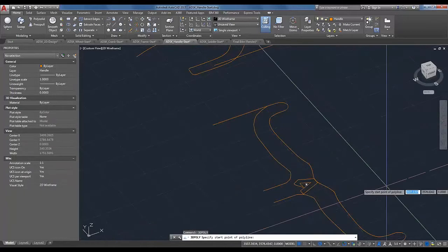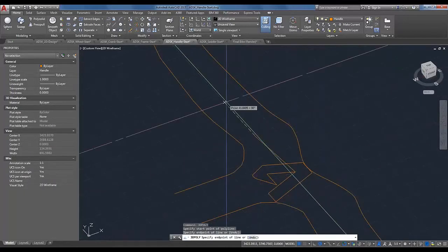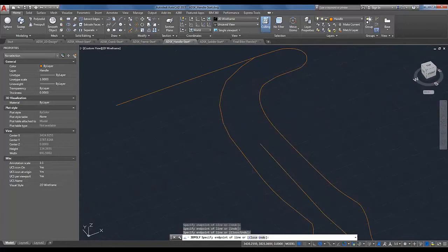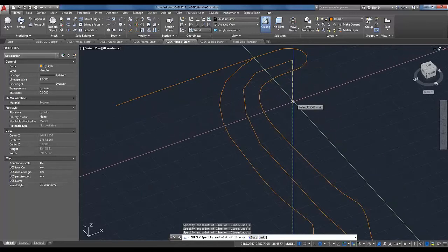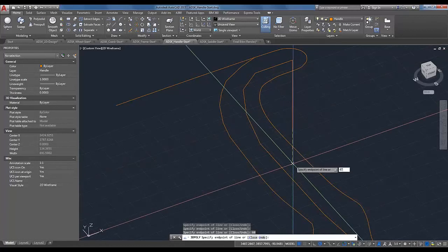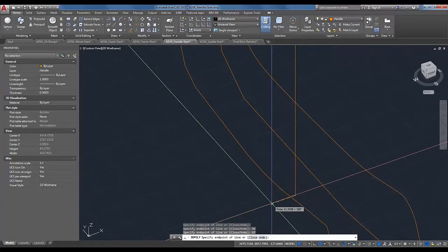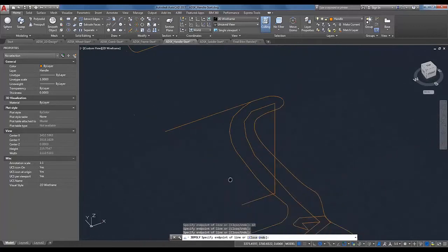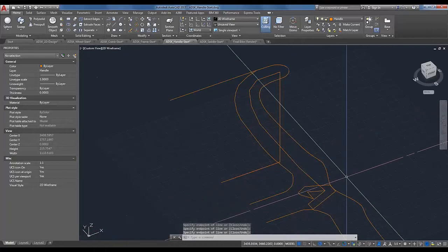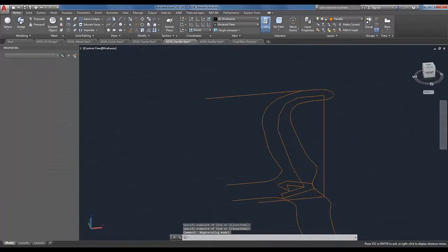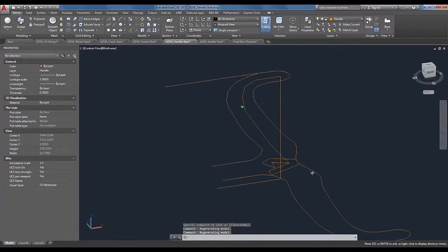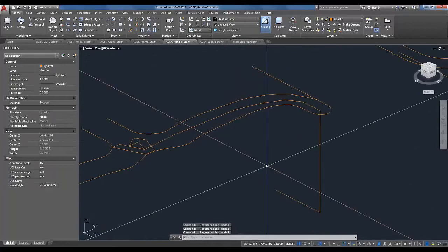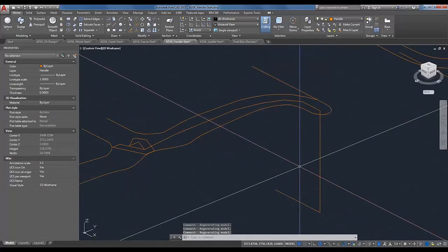3D poly. Going to create kind of a center line. I'm going to go down Z. Let's do 60 first and then 67. And then I'm going to go back, just creating some nodes along the way. Enter to exit out. And if I hold down the shift and center scroll button to swivel around, which is what I've been doing this whole time, you can see I have the start of a shape that I can use. It was really nice and rigid, which isn't going to do me any good.